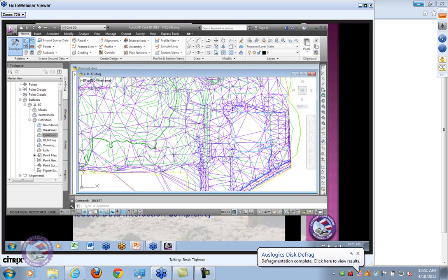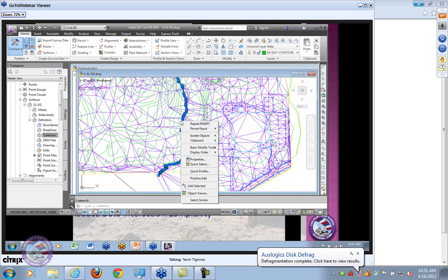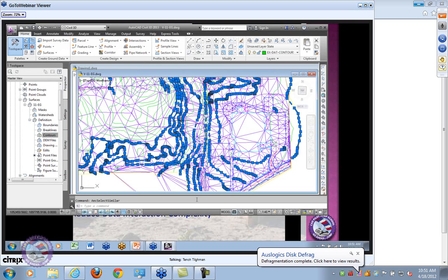Now, to do our contours, we need a selection set of those polygons. So I can grab one of these, and you see all of my nodes here, right? If I look at my property box, you'll find this is a certain kind of polyline, there being three kinds of polylines in AutoCAD now. I'd use select similar, and that gets most, but notice that there are these other contour things, which are 2D polylines.